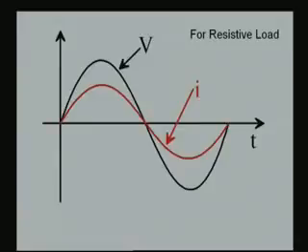And what is the process? We will multiply the voltage waveform and the current waveform. What do we get? The voltage is in volts, the current is in amps. When you multiply V and I, we get watts. So, we will produce the power waveform in watts, the instantaneous power waveform. So, we are going to produce the waveform P, which is equal to V I, by multiplying these two signals point by point, instant by instant.